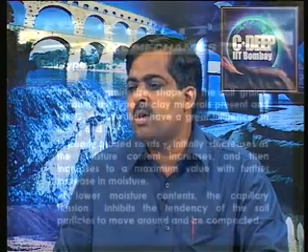And the specific gravity of the soil solids, for example, if it is of iron origin, then the specific gravity of the soil solids may be very high. Sometimes, if it is say fly ash, it can have a low specific gravity. So, the specific gravity of the soil solids also influences the dry unit weight and has a great influence on gamma d, the dry unit weight, and the optimum moisture content.